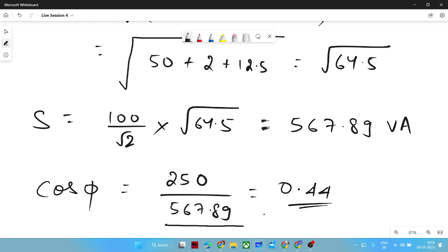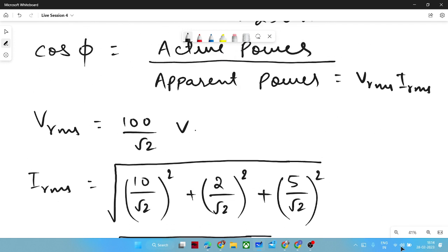That is huge since your power factor is not good. It is a really bad power factor, and it is a huge issue in power converters. For catering such a load, you need to over design the converter. So that is an issue that you should look for. That's the drawback of this kind of thing.